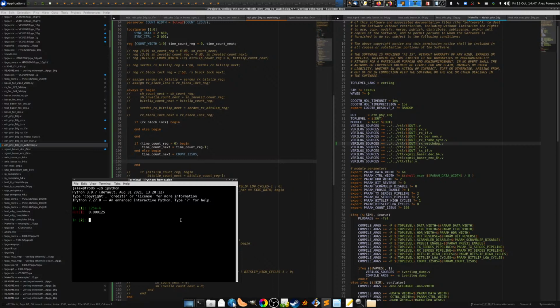And the clock period that we have is 6.4 times 10 to the minus 9. So we do this division, we get about 20,000 clock cycles. All right, and we can transfer 8 bytes in each one of those. So that is 156 kilobytes worth of data.